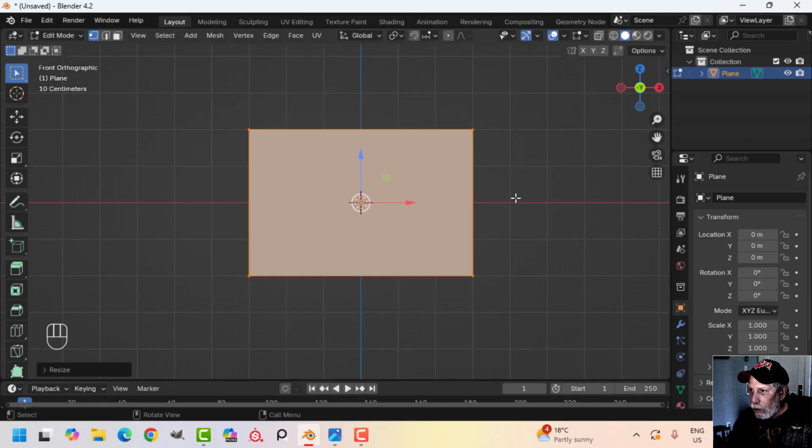And we're going to start with this. So I'm in edit mode and I've got the vertices selected. And if not, you can always press this button here or 1 to do that. And I'm going to bevel these vertices. And to do that, it's not just Control B, it's Shift Control B. So you can watch my keys down here.